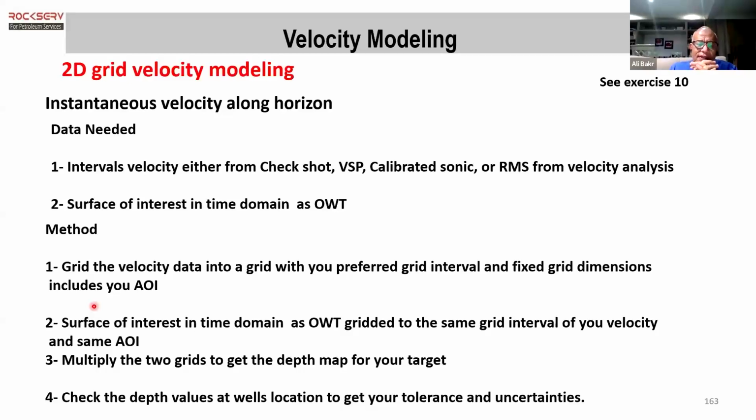And at those 4 wells, you have the depths of the layer. And you also have a velocity for that layer, the average velocity from top to bottom. If you do have an average velocity measured at the well, then you contour the values of average velocity all over the area. Of course, it's going to be very correct at the well location, and as you go away from the well location, it deteriorates more. But again, this is c'est la vie. We cannot do more than this.